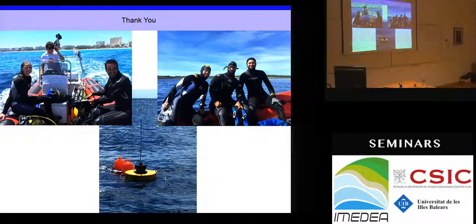This was my question. Do you really need the near bottom velocity to solve the dissipation? Yeah, I think if you want to do it properly, then, let's say for Posidonia, it's the near bed velocity. This XBeach model is a depth-averaged model. It doesn't really resolve the vertical structure of the flow. So there are limitations to the modeling approach, and I think there are many avenues that we can explore to make it better.